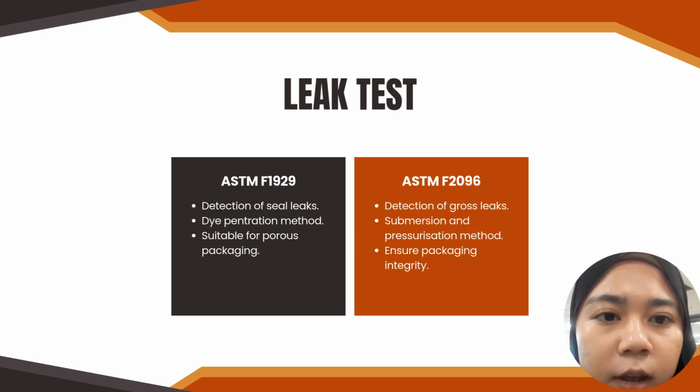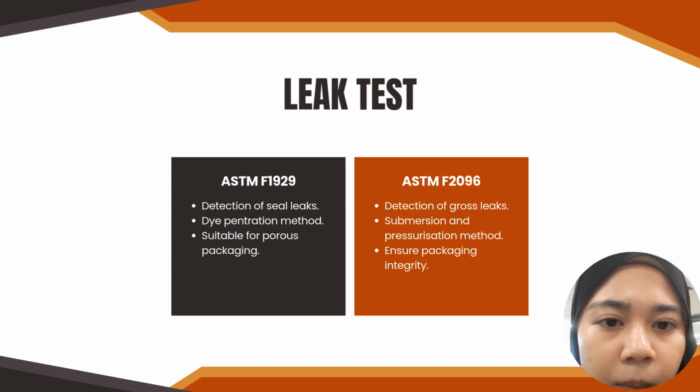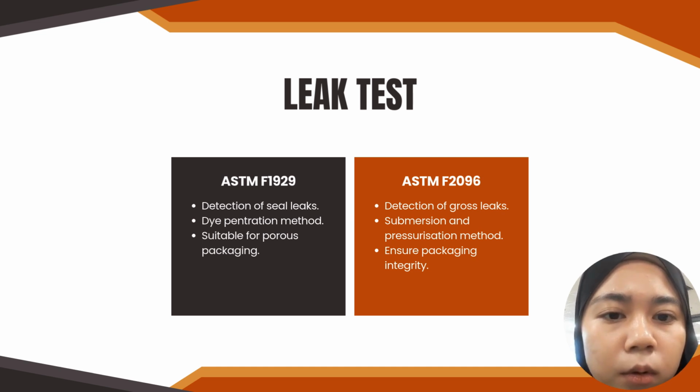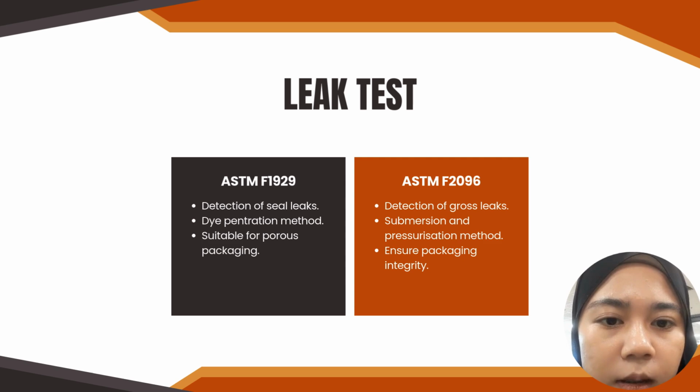It is used to detect gross leaks in medical device packaging by pressurizing the package and submerging it in the water. The presence of bubbles indicates a leak in the packaging, which could compromise the sterility, and this test ensures packaging integrity and protects patient safety.